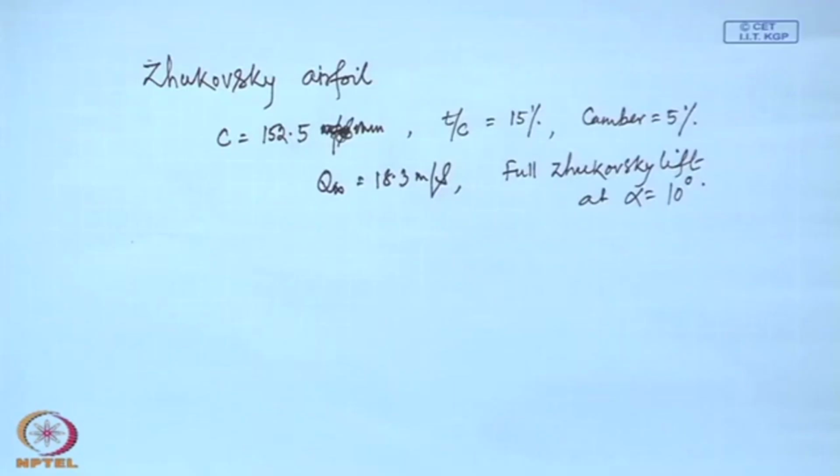Any suggestion? What I have discussed earlier? Since we are not in a position to solve flow over the airfoil directly, we have to transform this airfoil to a circle, which we did by Joukowsky's transformation. So, the first thing is we have to find the circle, along with the parameters of the transformation. Then we know the solution for the circle, so we can construct the solution for the circle and then transform it back to the airfoil.